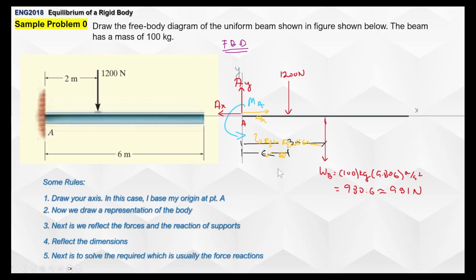Then obviously the next step here is to solve the required, which is usually the force reactions here, so to determine the AY and AX. And you do that by establishing force equilibrium and the moment equilibrium.